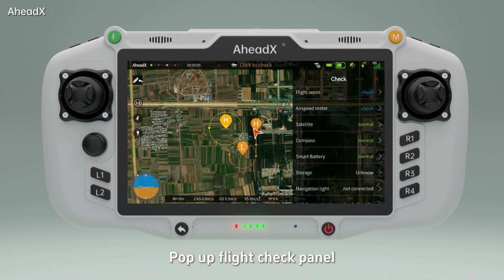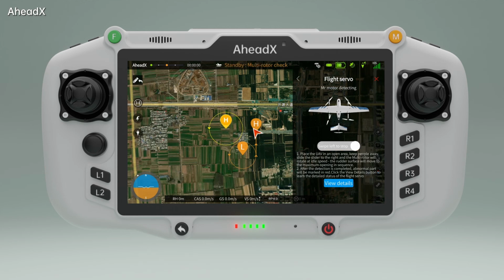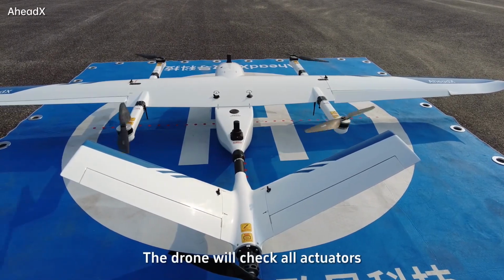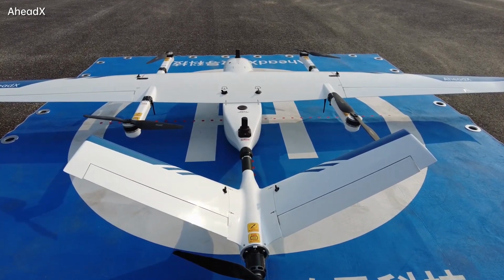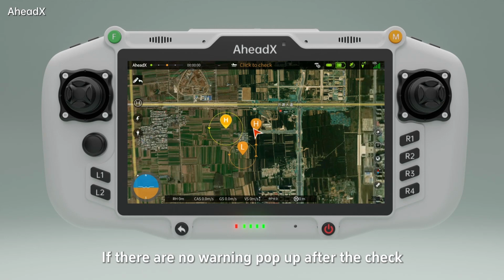The flight check panel pops up. Click on Flight Servo Check. Then slide the scroll bar to the right. During the drone's self-check process, ensure there are no safety hazards around. The drone will check all actuators, including motors and servos, for normal operation. If there is no warning pop-up after the check, it indicates that the actuators are normal.